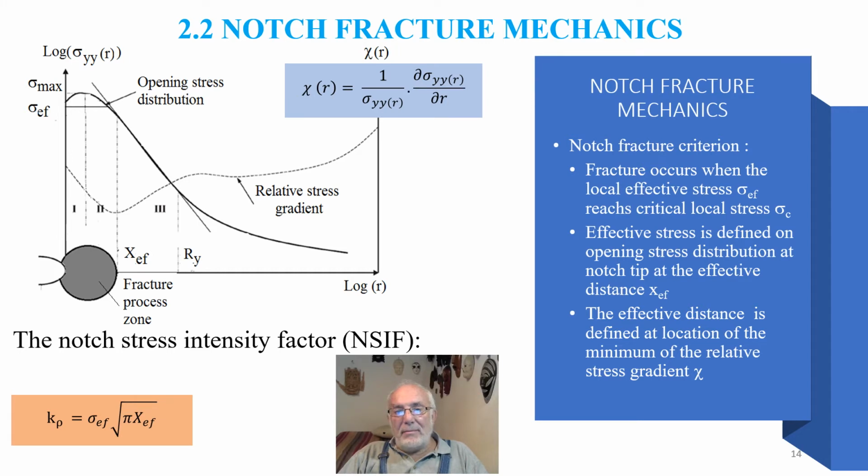We have made the assumption that the gouge is considered as a stress concentrator. In this case, we have to apply notch fracture mechanics to assess this defect. Notch fracture mechanics is based on a local fracture criterion. We need to know the stress distribution at the notch tip.